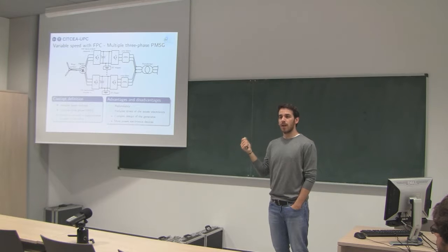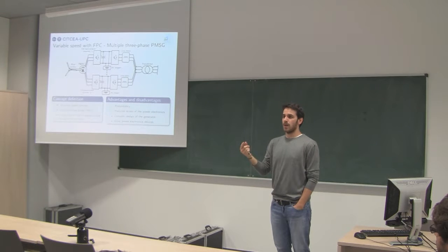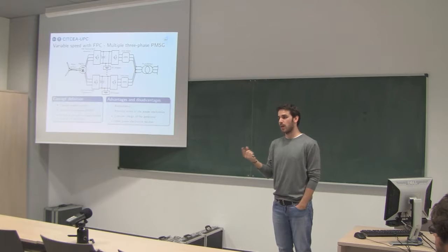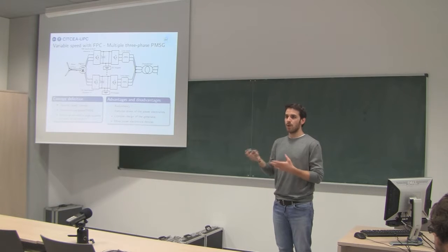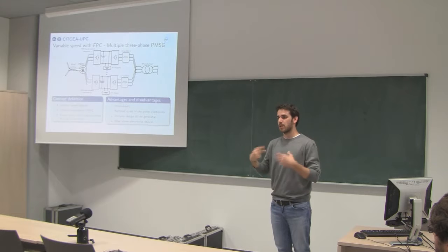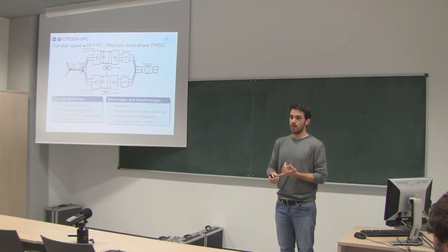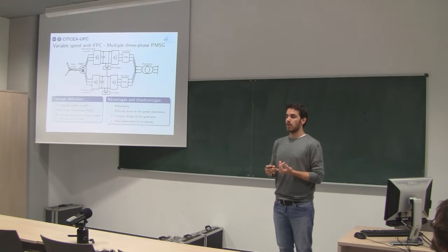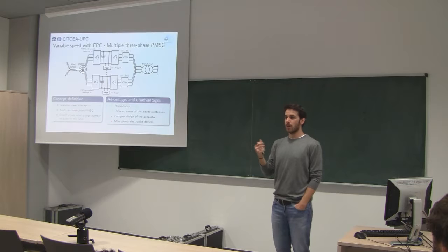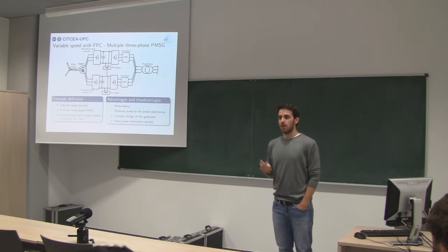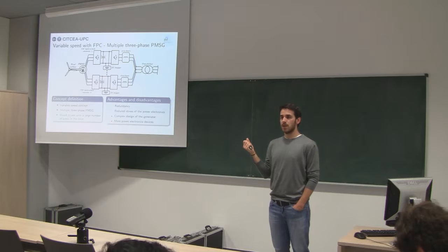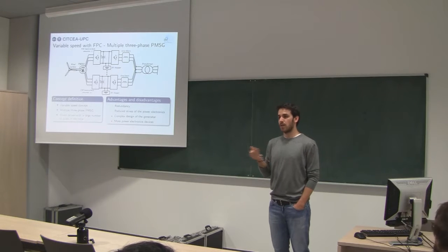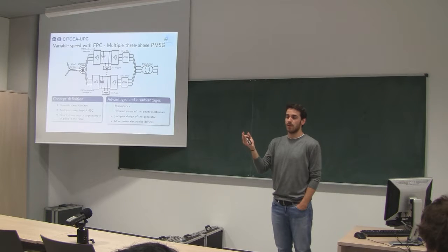This is done like this because, for example, if you have an offshore wind turbine, you have to imagine that it's difficult to do maintenance tasks in the middle of the sea, and even to repair that, it depends on the season of the year. It is difficult because it's not easy to go there with another huge converter and replace it. So it's a matter of cost, and what you cannot do is to lose one of these wind turbines. I mean, you cannot lose a wind turbine for, I don't know, a month, because you will lose a lot of money there. So they are proposing this. Basically, Alstom is proposing this topology because of redundancy. They can still produce some power even if they lose one of the stators.